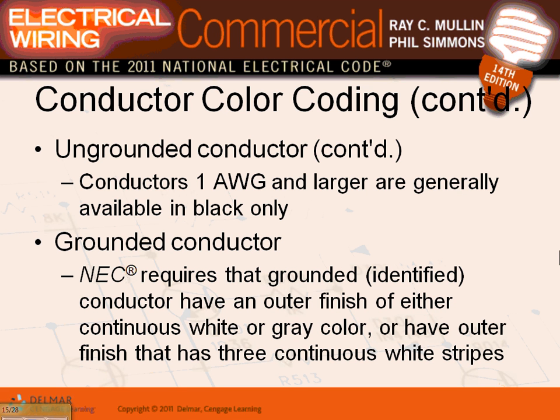The only time I need to identify this by color is if I have another voltage system coming to the building. Now I have a 480/277 and a 208/120, then this has to be color coded. It doesn't have to be color coded by insulation. I can put tape in the field, tape it with different colors. In a lot of industries, you can buy color-coded cables, but they are very expensive. That's why contractors buy black and use it for phase A, phase B, phase C, neutral, and ground, and they do exactly what I told you with the tape, they tape around it.